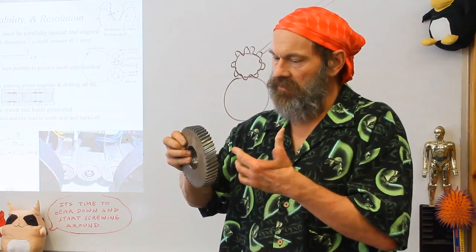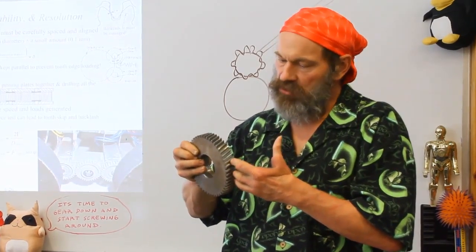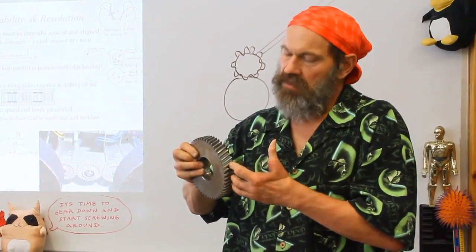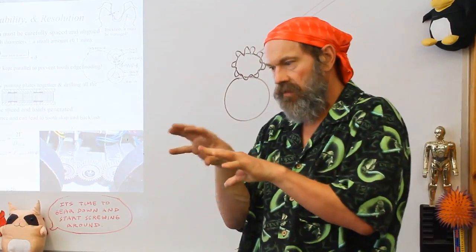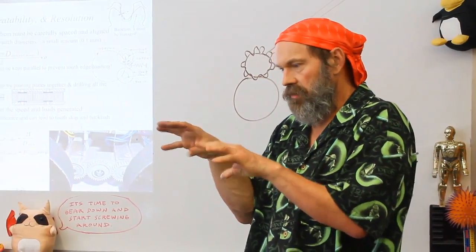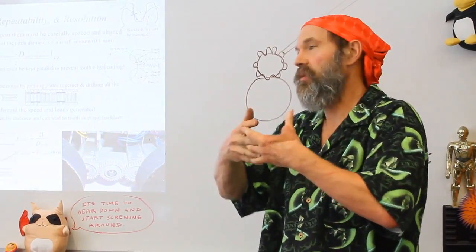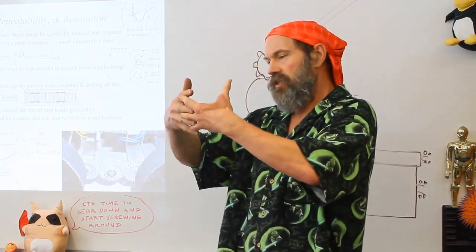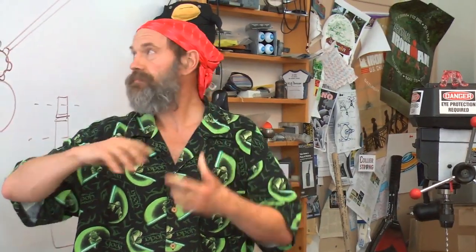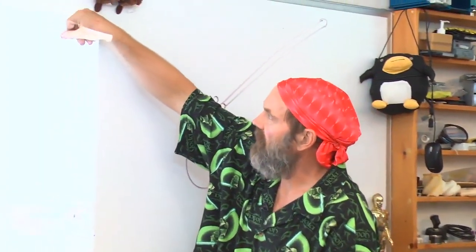If you happen to be so unfortunate to have put it together and pushed it together at the large point, when you rotate it, now that eccentricity between the bore and the pitch circle is going to really mash the teeth together and you could break them off. So you have to set your gears up with some center distance being a little bit larger than the average pitch diameters of the two gears. You have to set them up so you have some backlash.